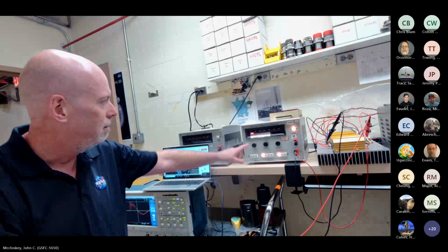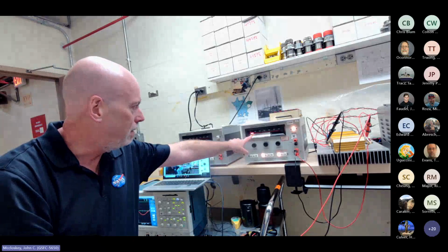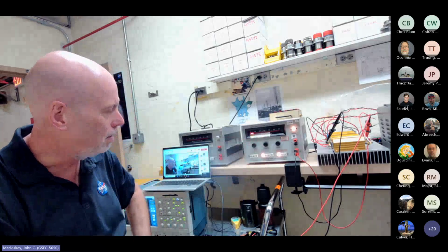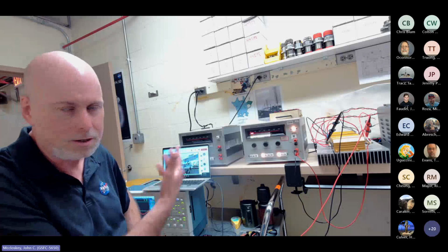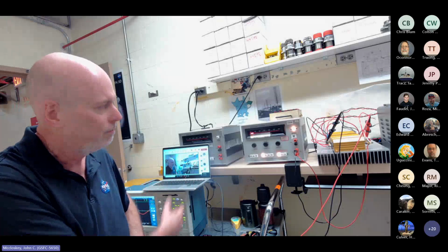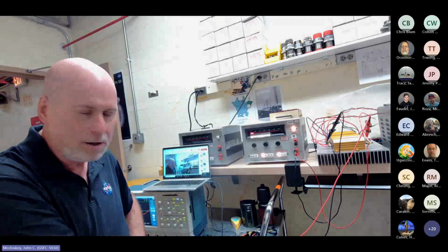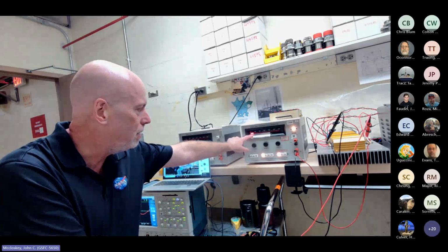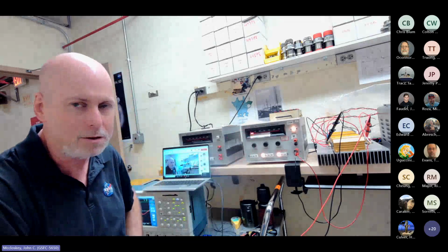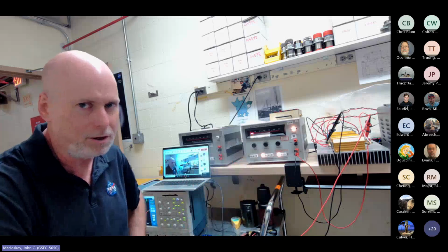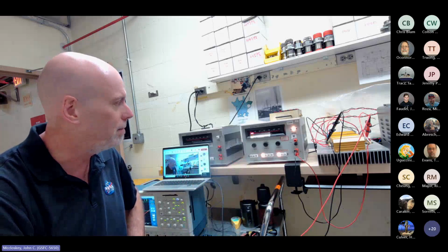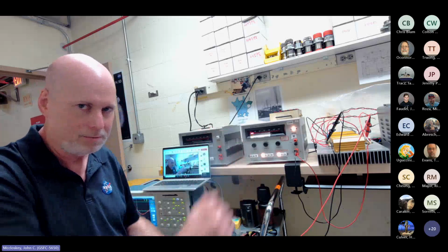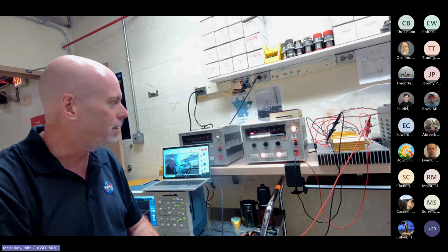But here again, these generators, the default specs in the mill standard, are to give you hundreds of volts, and we're generally hanging around about 30 volts. So we're at the low end of the drive capability, and most amplifiers like to be driven near the upper end. Certainly, RF amplifiers like to be driven pretty close to their capacity.